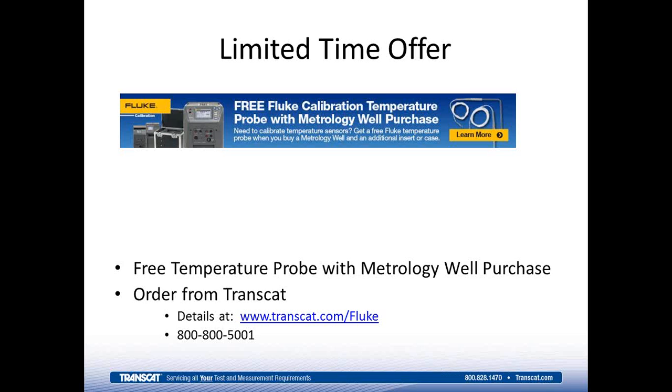Okay, the next question. Is there an immersion equation for thermocouples? Yeah, thermocouples are a little bit different animal. We probably won't be able to get into detail about this. We do have some webinar series around thermocouple calibration, but a good rule of thumb if you're doing comparison measurement is to put the junction of the thermocouple, or the tip of it, in the center of the sensor of whatever you're comparing it to.